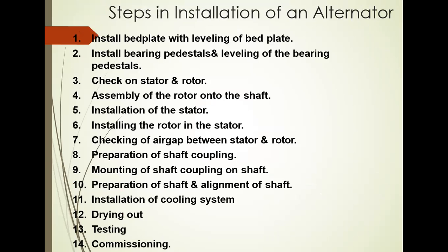Then what are the steps needed for installation of the alternator? Initially, the bed plate, denoted in blue color in the previous slide, right? So first install the bed plate with leveling of the bed plate. The leveling also is to be considered.